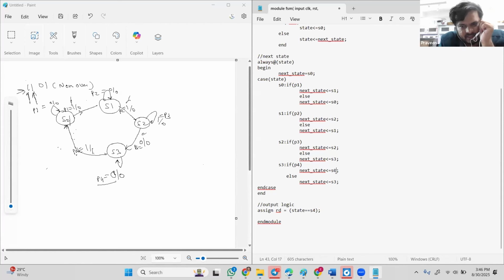What do you want to say here? What should I write? Ma'am, can I attend? Yeah, please. Actually, in S3 state, you considered P1, P2, P3, P4. I think that's not necessary. You can consider only one data, P1 or P, anything one. If it is low, it is going to the next state. If it is high, it is going to the next state. That will be decided by only one bit. But you have considered P1, P2, P3, P4, that is four different bits.